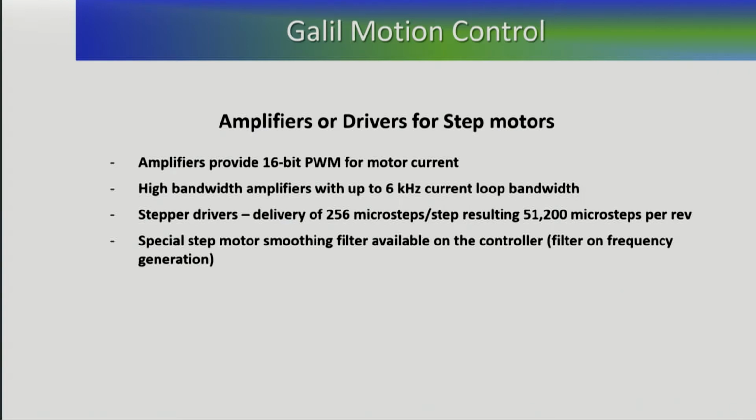In order to work with the motors that have a load time constant as discussed earlier, you also want to be able to take an amplifier that has a high current loop bandwidth so that you minimize the delays. And in this case, look at amplifiers that can basically give you a high current loop bandwidth to be able to work with your highly responsive systems.